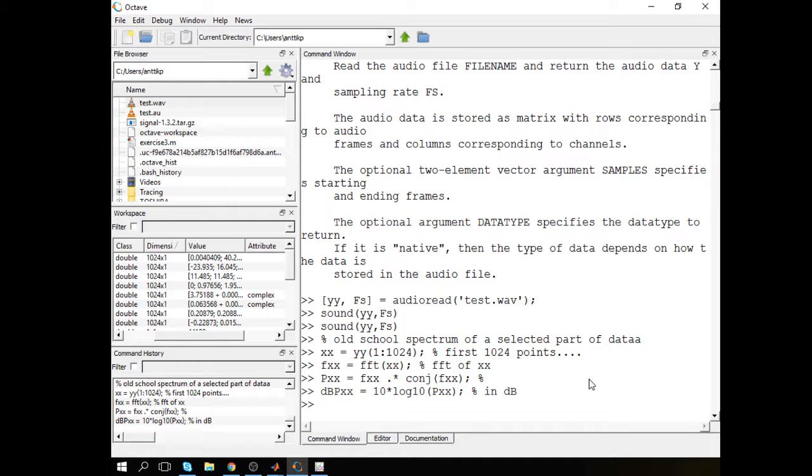So that's your scaling right there. If you want to calculate the real frequencies, you have data from 0 to 1023. 0 is the first frequency, so offset by that one, divided by 1024, multiplied by sample rate.